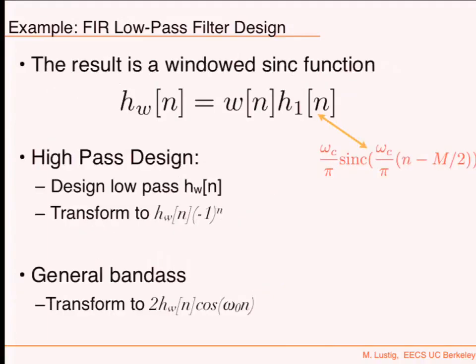All right. So this is also called a windowed sinc filter, right? Because if you want a box in the frequency domain, then of course you're going to take a sinc and you're going to window it. And so this is the windowed sinc design. You window it by a certain window, and that's pretty much it.